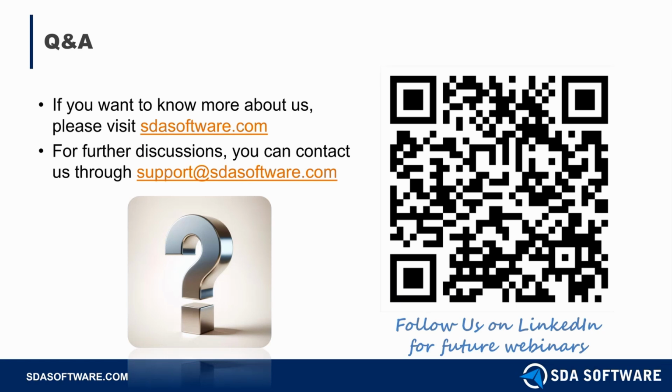So I see there's a question here. We have a person asking why we chose the coupled flow solver and not the segregated flow solver since the analysis is subsonic. So the reason is, for this particular case, we actually went in and checked whether there is a difference between using the coupled flow solver or the segregated flow solver. The answer is that it was less than 0.01% change.